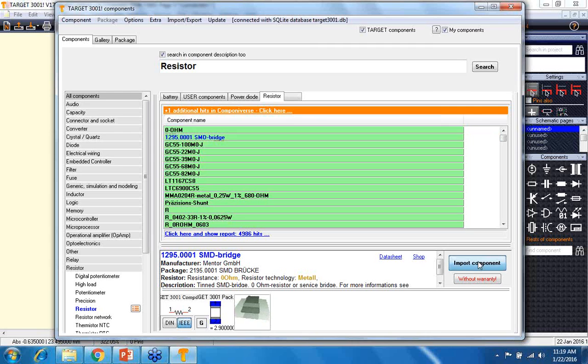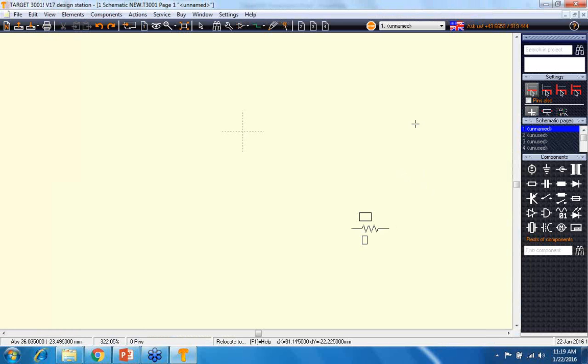When you import a component, it will come here. So we'll make one short circuit to give you an overview of the working of the software. Just place one resistor here, and there are some other component libraries given here according to their package type, like the power source, ground, connectors, resistor, inductor, diodes.